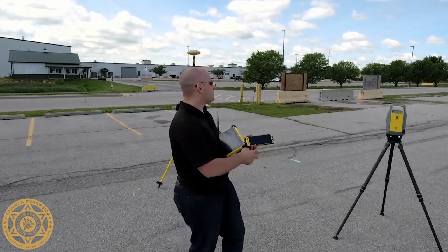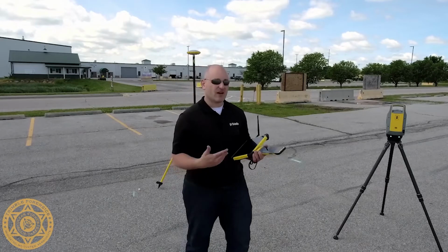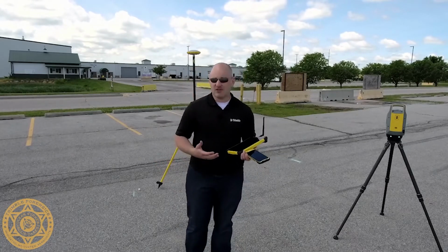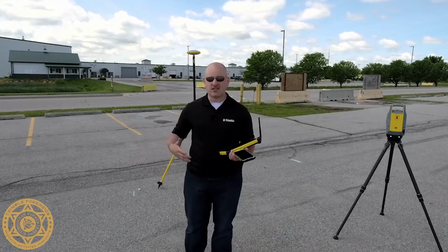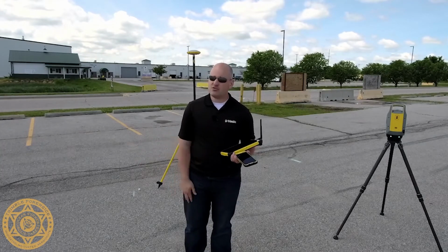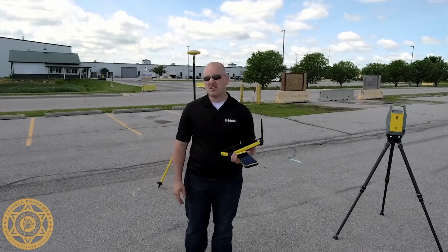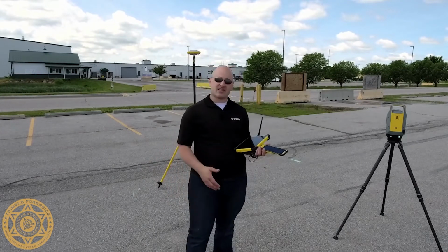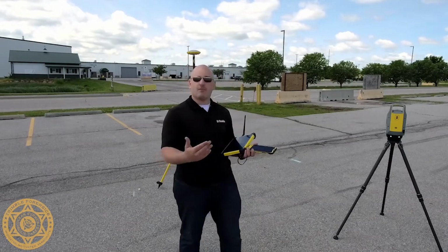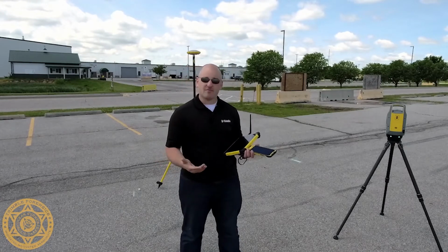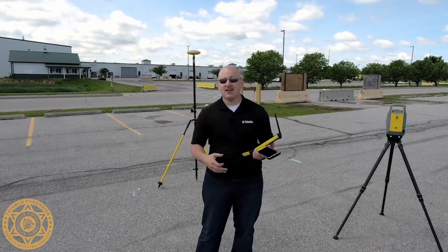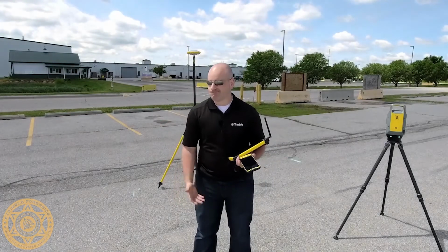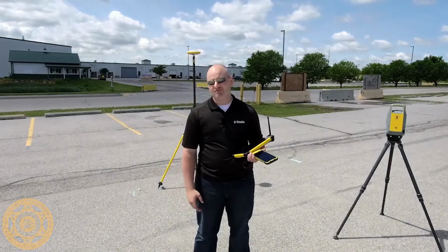Okay? And this is just one example. If these were ABS marks, again, we know that ABS marks are even fainter yet. Some of those ABS marks are really hard to see where they begin. How much could you be missing? Are you missing the mark? Again, that's a question to ask yourself if you don't have a scanner with the ability to take a precision point. If you don't have another means, such as using GNSS, to document where those marks actually start, what are you missing? It's a good question to ask yourself.